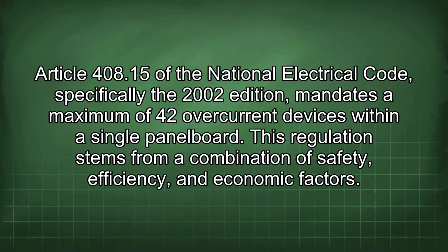Article 408.15 of the National Electrical Code, specifically the 2002 edition, mandates a maximum of 42 overcurrent devices within a single panel board. This regulation stems from a combination of safety, efficiency, and economic factors.